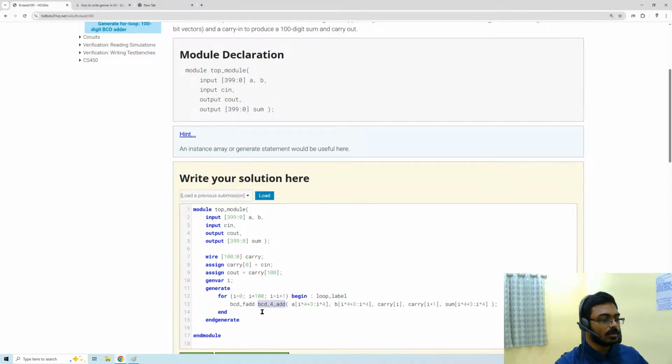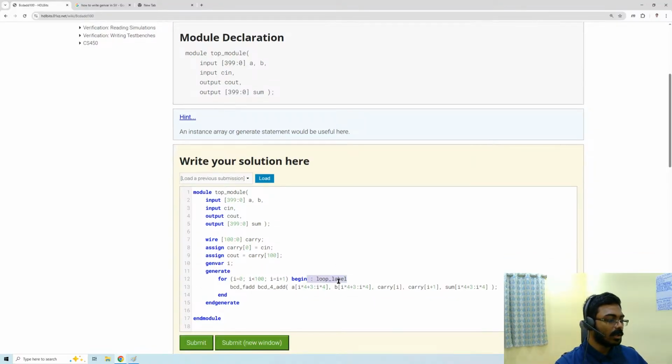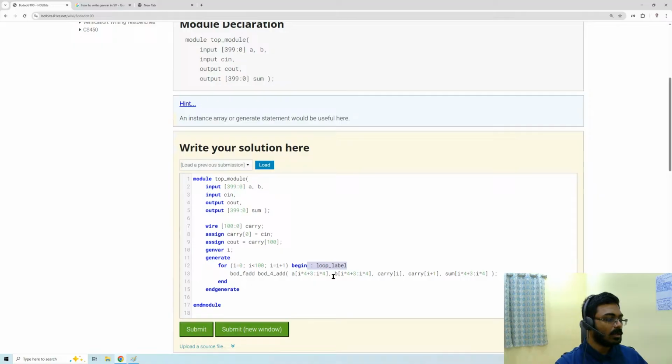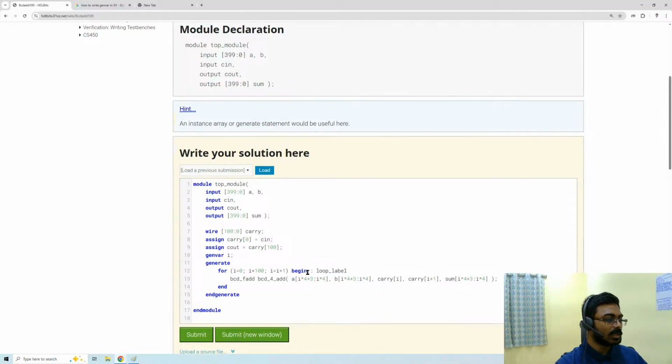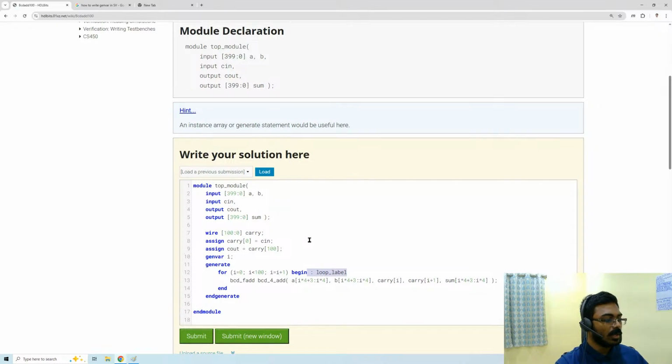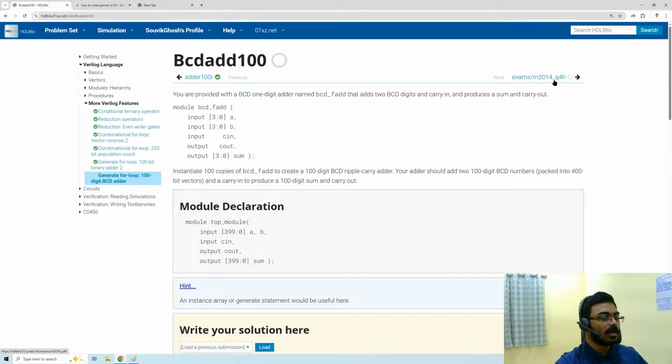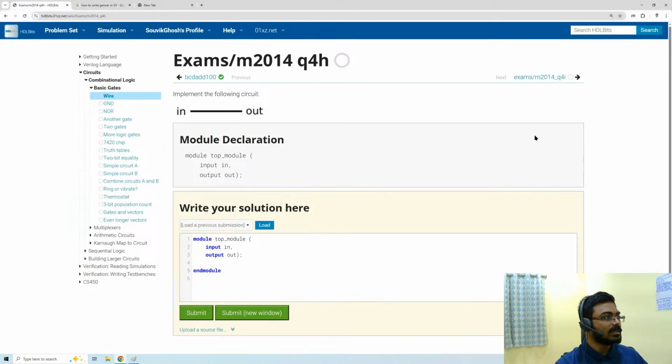So this should not be needed, but okay, they have some code which says these all things are needed, basic checks without which it will not run properly. So maybe this is the case only for HDLBits because I didn't see this in ModelSim and even Synopsys VCS. So okay, it's good that we understand the error message and we can change things accordingly.